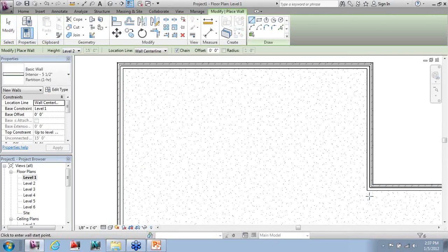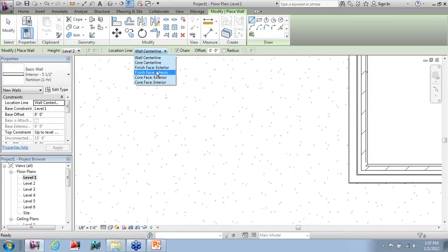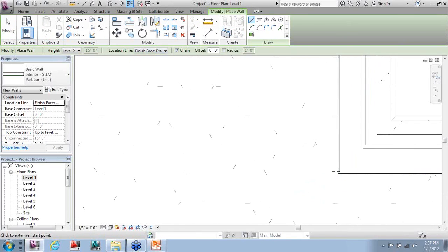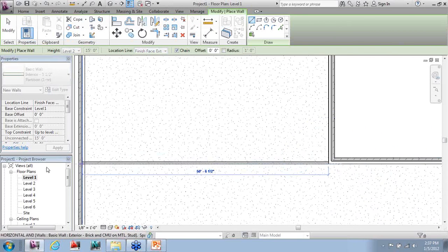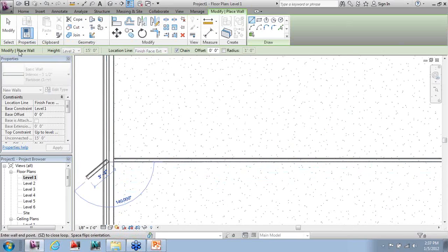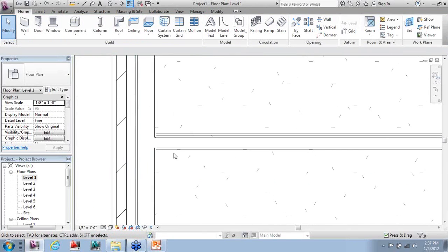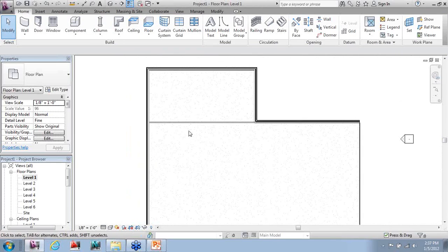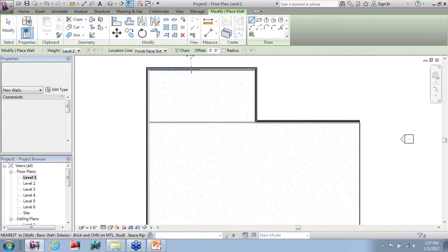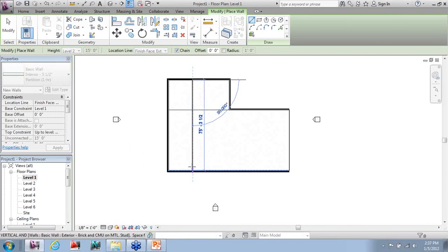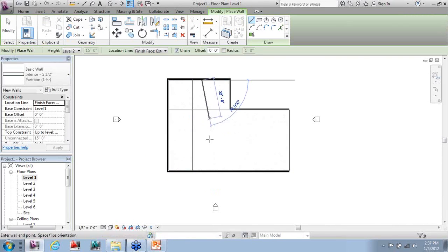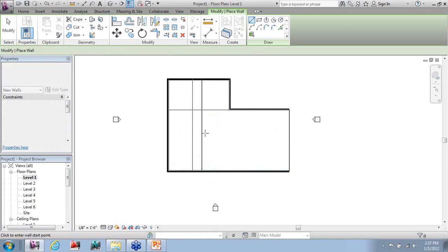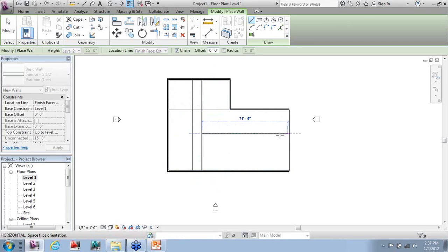Again, I'm going to use the Wall tool, and I'm going to start drawing some walls into my structure. You'll notice as I draw these walls, they start to automatically clean up with one another. Regardless of where I place them, there are cleanups occurring. This is a really great feature inside the Revit program that lets us create these quick cleanups. Very quickly, I'm going to generate a few walls in my structure, and then from there we'll start placing in some doors and windows.